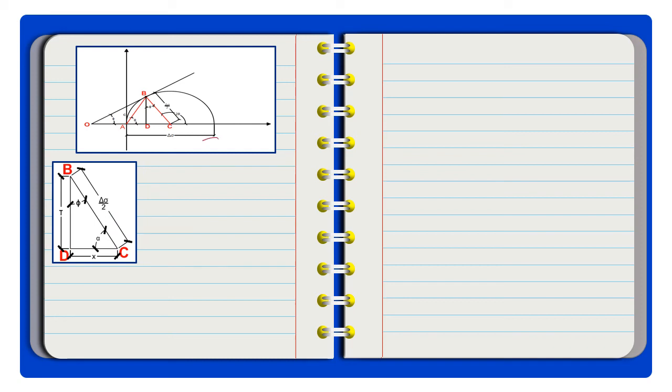The first thing we will get is the shear stress of the soil, or the shear stress at failure. As you can see, for the angle of internal friction, the adjacent side is tau, and we already have the hypotenuse, which is delta sigma over 2. So we could use the cosine function. Cosine of phi is equal to tau divided by delta sigma over 2.